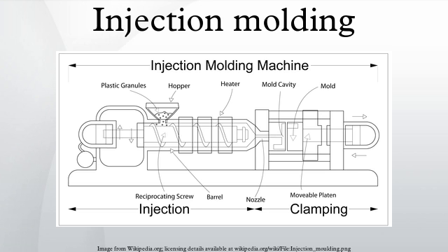To allow for removal of the molded part from the mold, features must not overhang one another in the direction that the mold opens, unless parts of the mold are designed to move from between such overhangs when the mold opens. Sides of the part that appear parallel with the direction of draw, or insert is parallel to the up and down movement of the mold as it opens and closes, are typically angled slightly, called draft, to ease release of the part from the mold. Insufficient draft can cause deformation or damage. The draft required for mold release is primarily dependent on the depth of the cavity. The deeper the cavity, the more draft necessary.